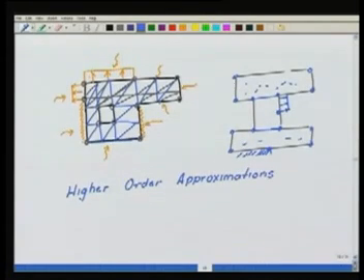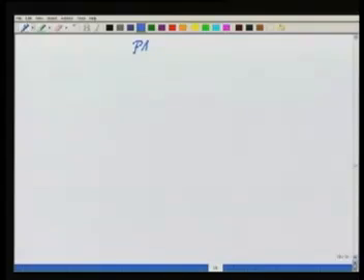Okay. So when we are talking of higher order approximations, remember that again we will be talking of these piecewise polynomials. So the issue of completeness, the issue of linear independence, all these issues will have to come up. So as far as 2D is concerned, the higher order polynomials are given. See which monomials have to appear in a given polynomial. All the monomials which have to appear in a given order polynomial for that representation to be complete is governed by something called the Pascal triangle.